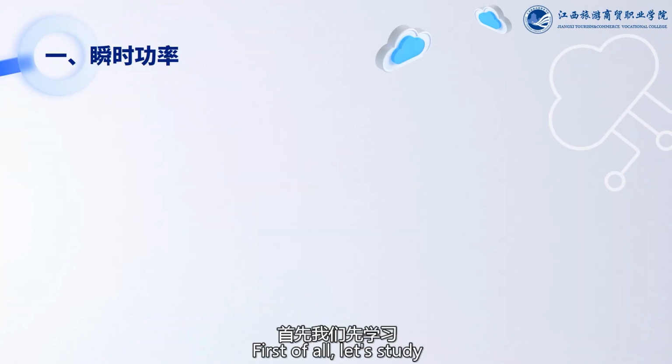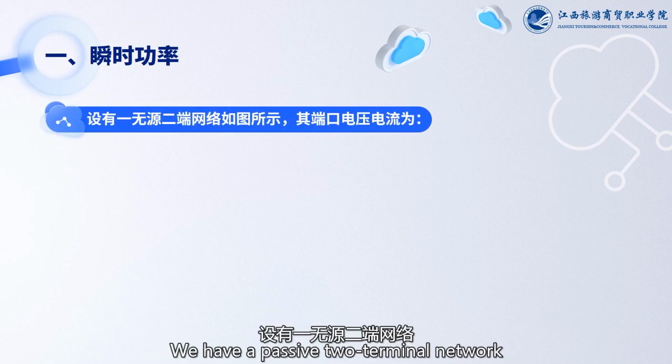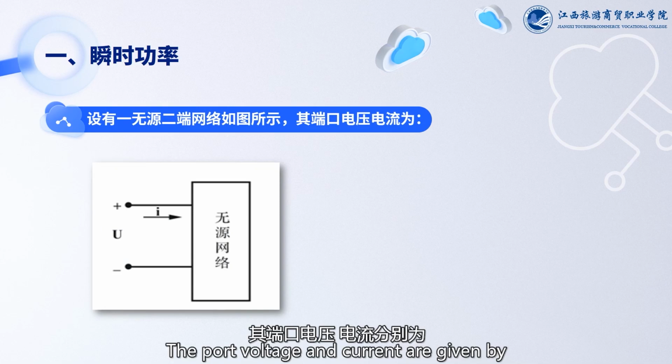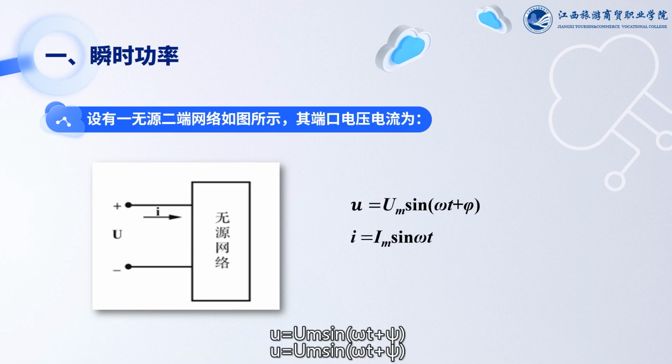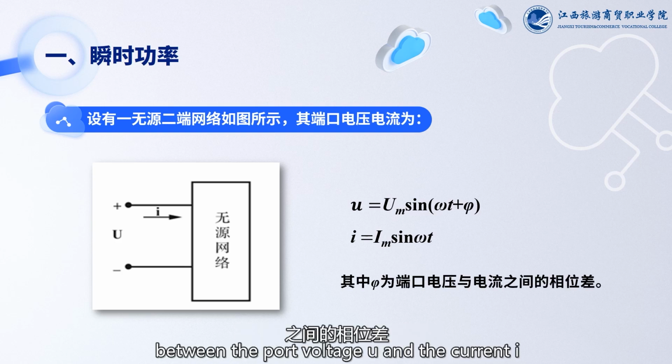First of all, let's study the instantaneous power of a sinusoidal AC circuit. We have a passive two-terminal network. As shown in the following figure, the port voltage and current are given by u equals Um sin(ωt plus φ), and i equals Im sin ωt. Here, φ represents the phase difference between the port voltage u and the current i.